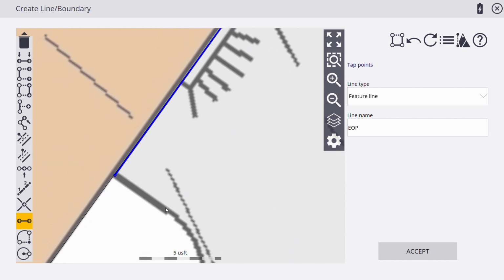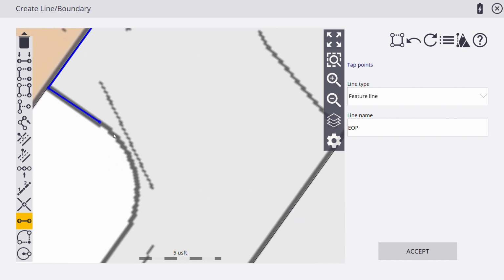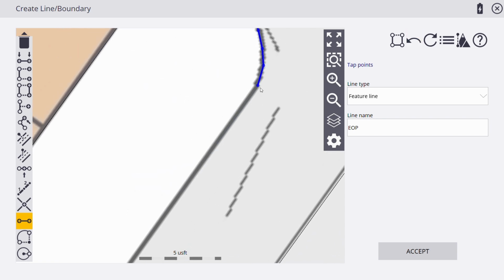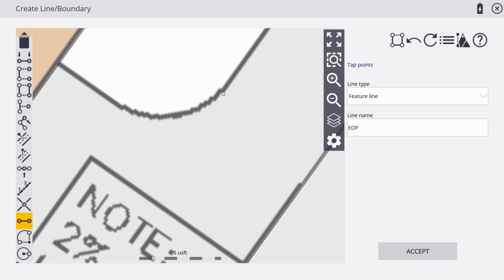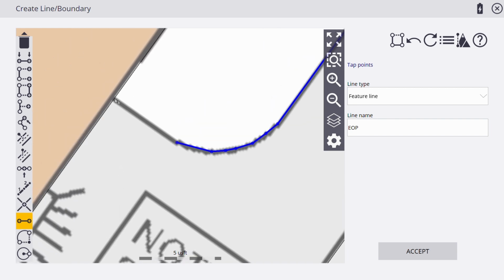But what's nice is all in one sitting we can show up to a site, get set up, situated, reference a couple of points, do an existing ground topo, and what I'm going to show you is actually a cut and fill between the two, to get us moving and to confirm that we are doing what we've bid on.